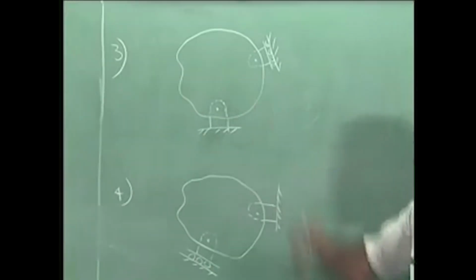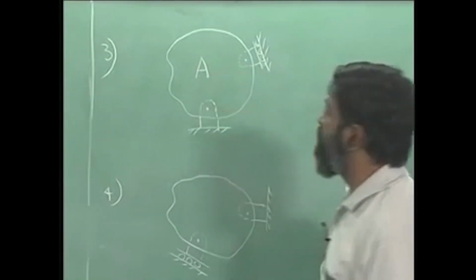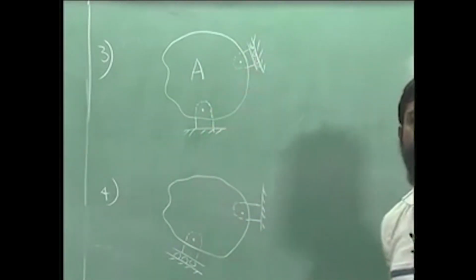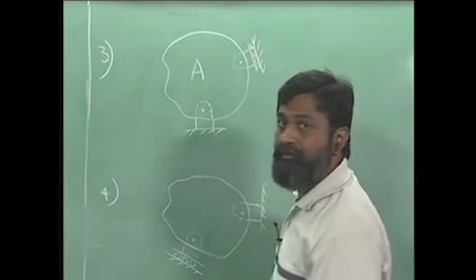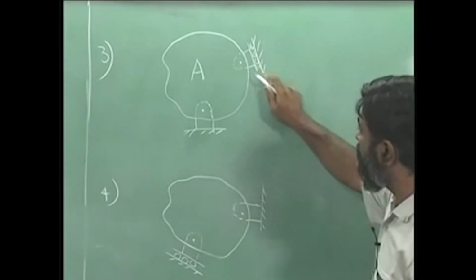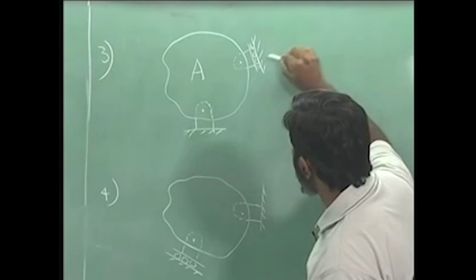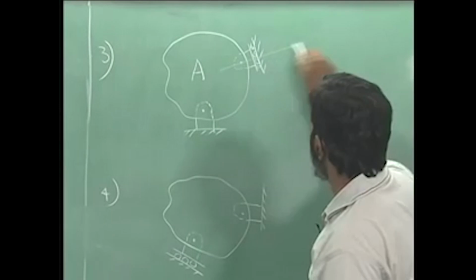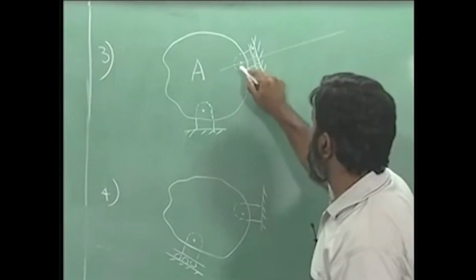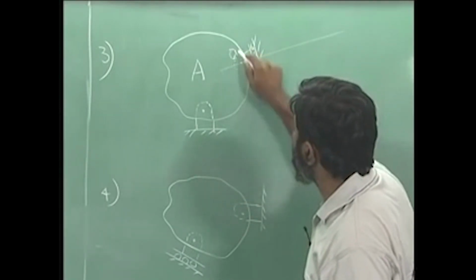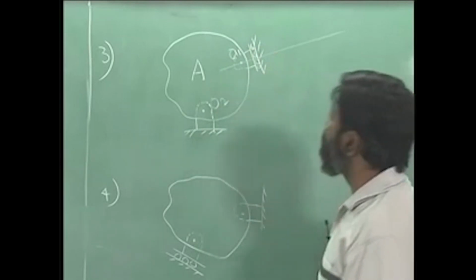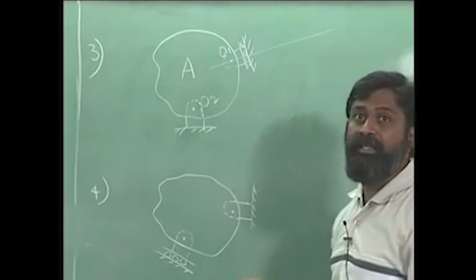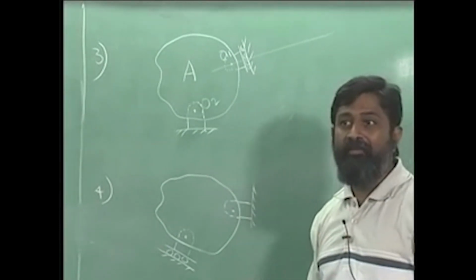Let us look at this example. This is a single rigid body. Naturally if I do not have any constraint, unconstrained motion, I will have 3 degrees possible, alright. If you look at it, I am arresting motion of this particular body A with respect to this direction. Let me call this as O1 and this as O2. I am arresting a direction motion here, which means there is 1 degree of freedom that is lost.